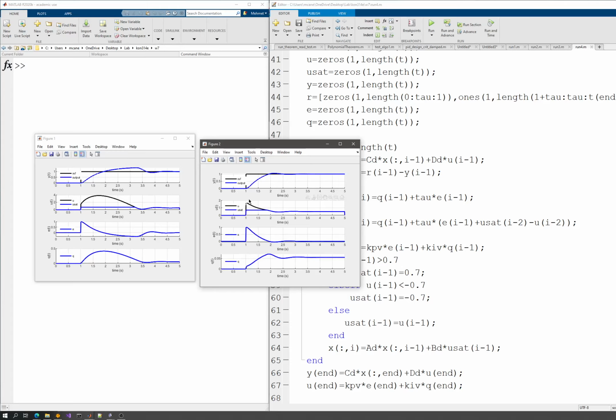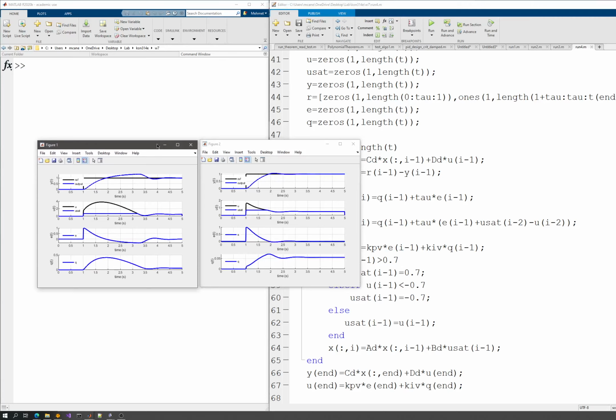We have a saturation, we have a jump, but at that point we are aware of the actual error and integral value of the error. So we are decreasing our control signal because we are approaching the reference. So my error becomes lower. If the error becomes lower, my integral should not be that big, and it just decreases its raw value. So at some point it enters the linear region of the saturation element, so it applies directly what the control signal on its own was. So that's basically the important part of our implementation.